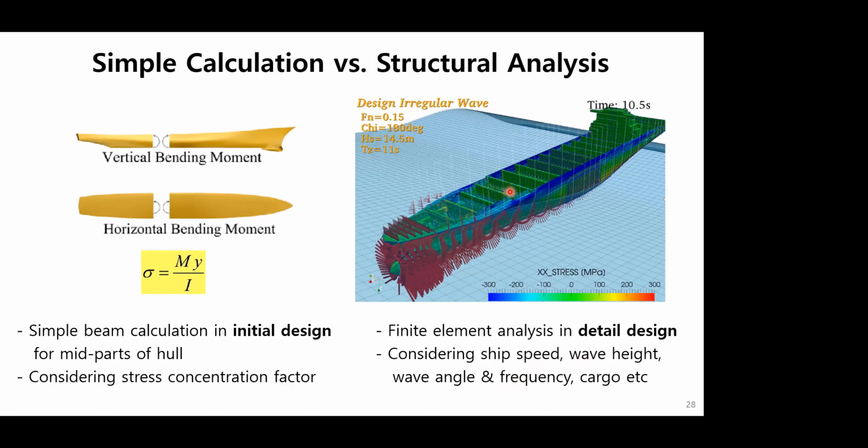This figure shows just one case of analysis loading under wave angle 180 degrees, wave height 14.5 meters, wave period 11 seconds. And actually, we need to carry out a large number of structural analyses for all loading conditions.